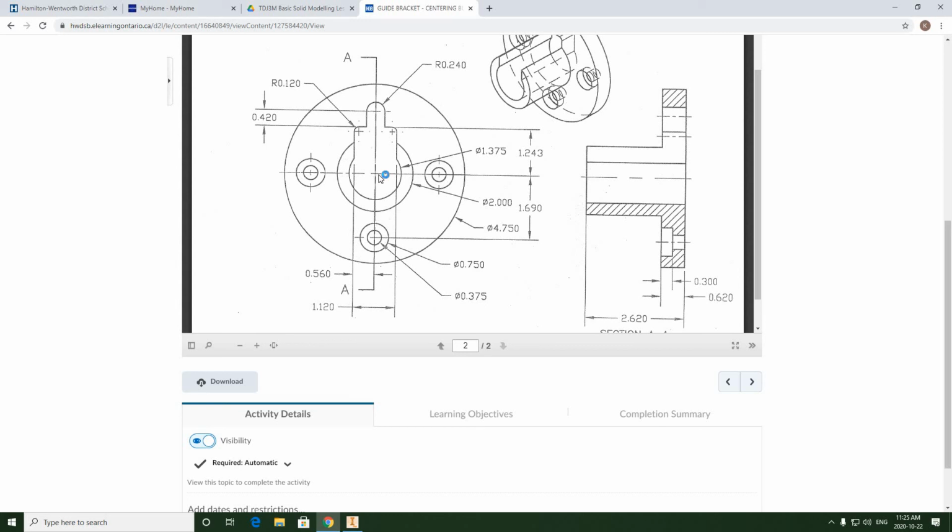Because there's holes going through these hubs, and there's a counterbore hole here, there's a slot here, this cutting line is going to be passing through dead airspace in certain sections. That's what you're seeing here. This is the open space of the hub. This is where the hub opens up to meet this slot extrusion at the rear. And then this is what the counterbore will look like in a sectional view as well.